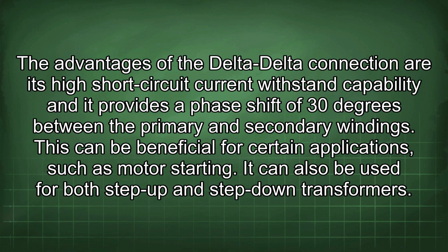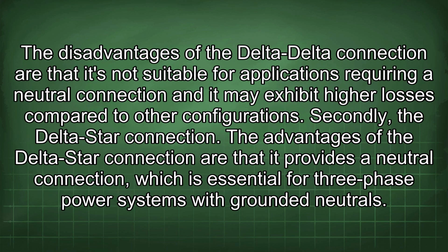This can be beneficial for certain applications, such as motor starting. It can also be used for both step-up and step-down transformers. The disadvantages of the delta-delta connection are that it's not suitable for applications requiring a neutral connection, and it may exhibit higher losses compared to other configurations.